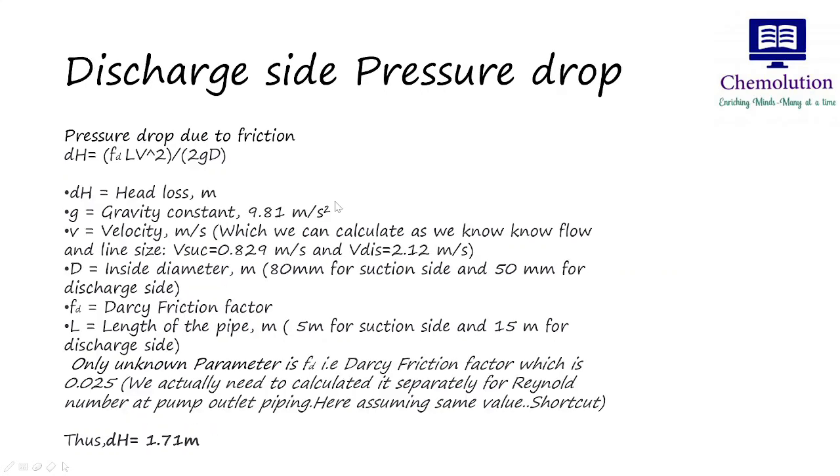Okay, so the next step is the discharge side pressure drop. Now I have taken a shortcut here. We would have to find Darcy's friction factor in the way we found it for the suction side. You will have to find it for the discharge side also. I have considered the same friction factor for ease of calculation and to shorten this video to some extent.